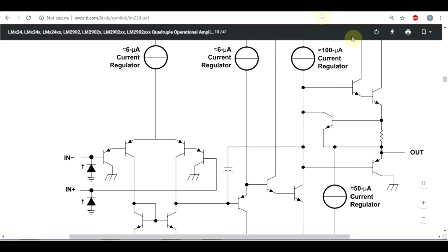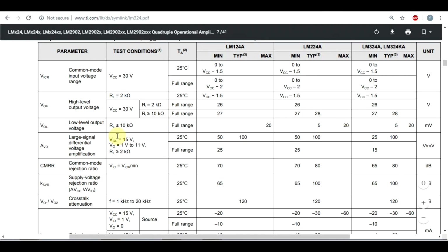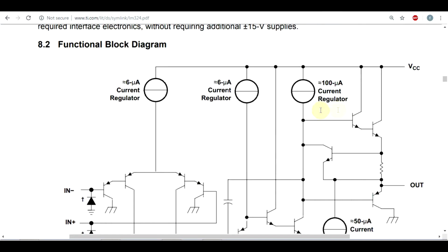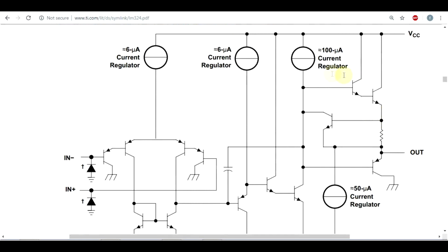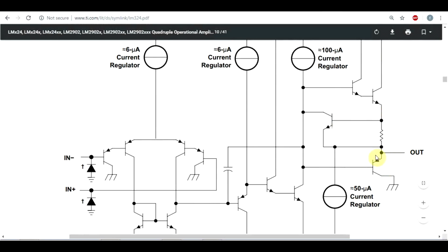And there would be one more thing to mention. We have seen that the output voltage is defined for different loads with different values. So why isn't the voltage the same for any sort of load? Well, this comes from the gain of the transistors and from any sort of protection circuitry built into the OpAmp's output. If this OpAmp would work with any currents, then it would most likely destroy itself. So after a certain current, the output stage will not be able to work.